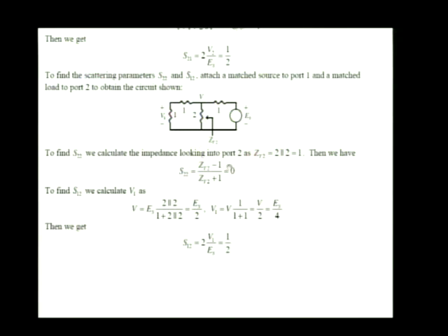Okay, well, what's that input impedance? Now the input impedance is equal to the 2 ohm resistance in parallel with 1 plus 1. That is to say, 2 ohm in parallel with 2 ohm, 2 in parallel with 2. That's the way I write it here. 2 times 2 over 2 plus 2, 1. So there's ZT2.